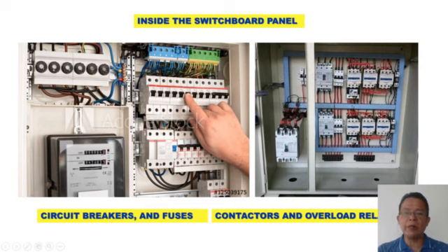The unlocking of an electromagnetic contactor can be done through the thermal overload relay under fault conditions. If any error takes place, then the holding contactor gets deactivated. Therefore, the DOL starter separates the induction motor from the mains supply.